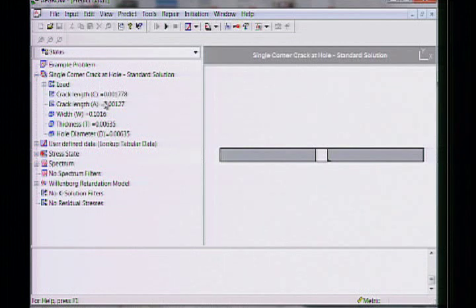And if you wonder why we have temperature there, it's just because historically we had a bonded repair capability where we had composite bonded patches that were cured under temperature. So we were concerned about the differences that happened to the thermal expansion, so we had to include temperature.